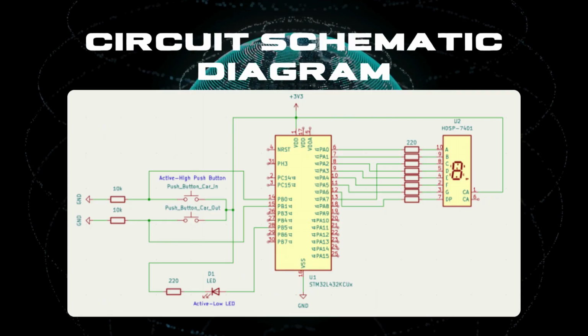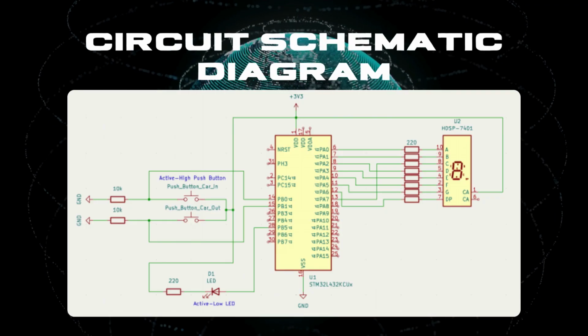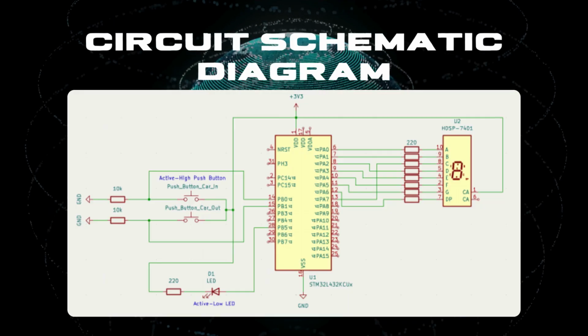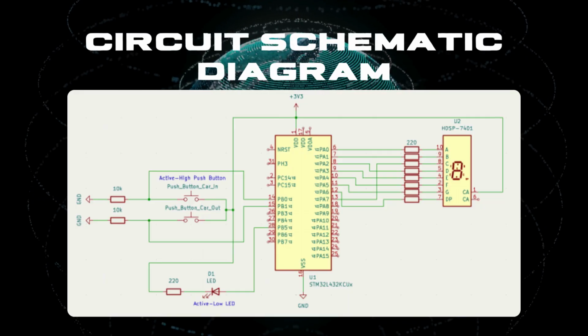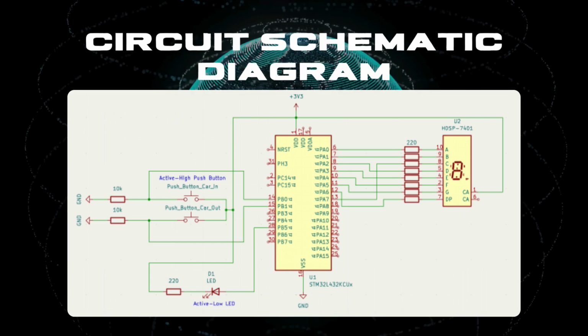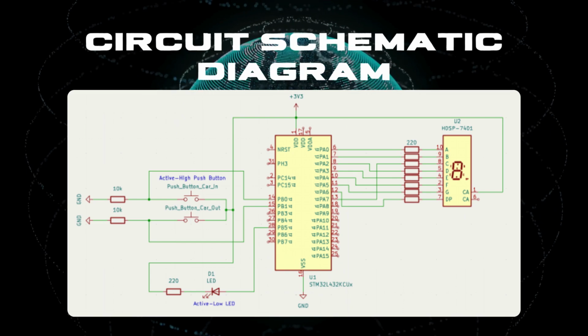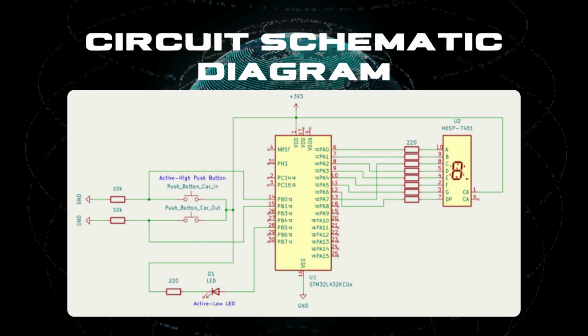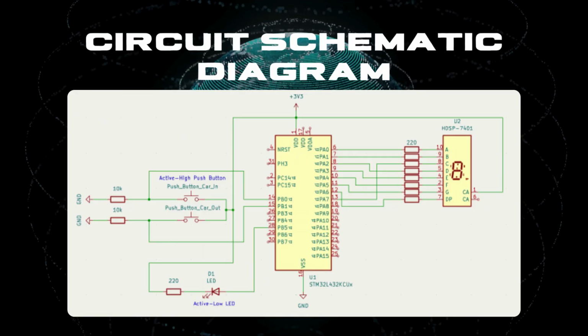For the 7-segment display connection, which is using all of port A, PA0 connects to segment A through a 220 ohm resistor, PA1 connects to segment B through a 220 ohm resistor, PA7 connects to segment C through a 220 ohm resistor, PA2 connects to segment D through a 220 ohm resistor, PA3 connects to segment E through a 220 ohm resistor, PA4 connects to segment F through a 220 ohm resistor, PA5 connects to segment G through a 220 ohm resistor, and last, PA6 connects to the decimal point through a 220 ohm resistor.